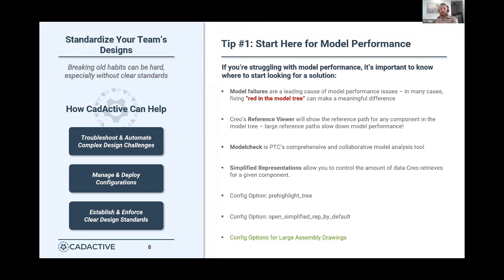Number two is understanding references. Once you've removed those errors from your model, it's important to understand how your model is referencing the different components within it, right? How can we trace what you're actually asking Creo to do when you bring a component into memory? So understanding those dependencies and reference paths can make a really big difference in how the model performs.